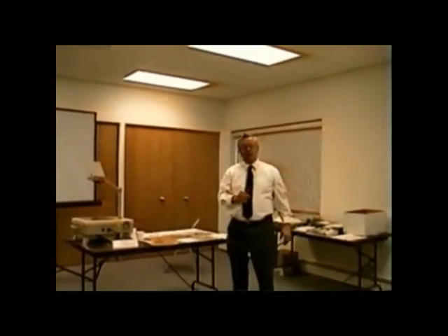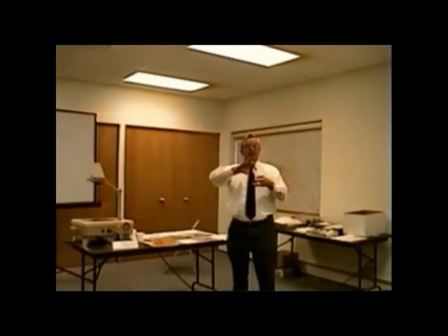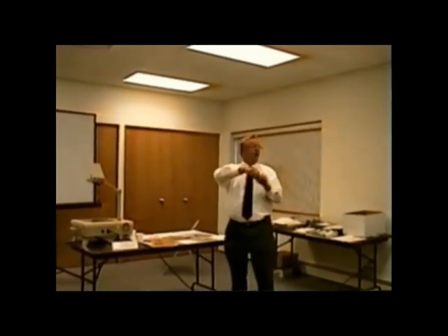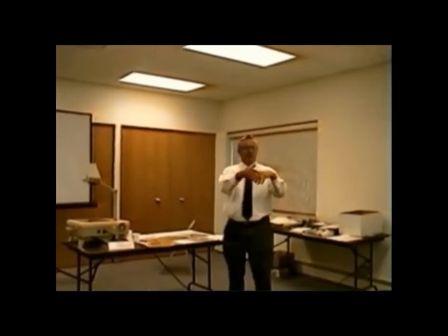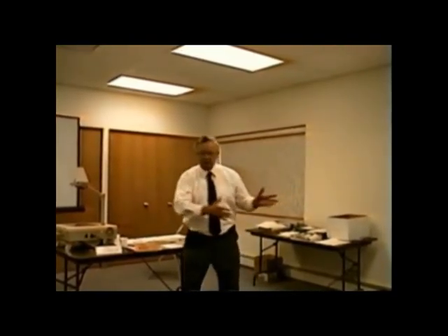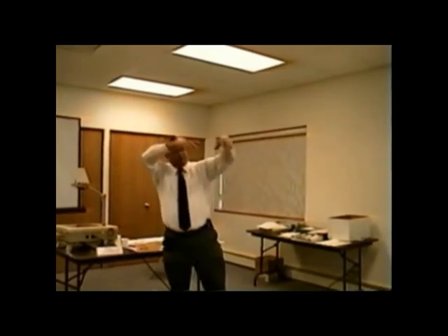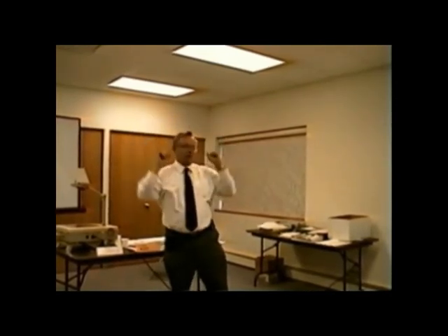We did this class for a contractor who's been installing a lot of new housing, and for whatever reason, he never knew that an 80 plus was negative draft. And so for that reason, he wasn't even following the rules. You're supposed to use B vent, not single wall. But he was putting single wall together and putting some kind of adhesive in there to seal them. I said, why are you sealing it? We're going to tell you to poke a hole. He says, well, because combustion products will be coming out of the seams. I said, no, this is an 80 plus furnace. So a 78 and an 80 plus are all negative. The chimney's negative. The vent from the furnace all the way up is negative draft.